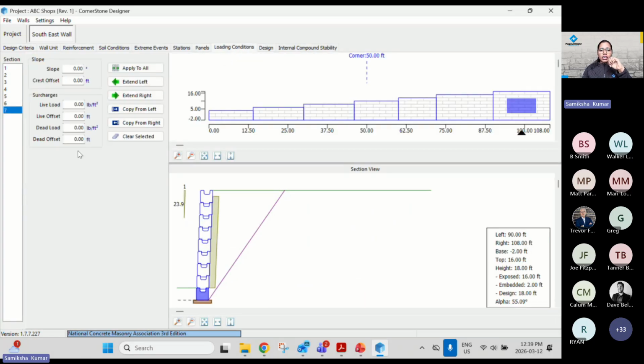Okay, now loading conditions. Very important again, very versatile depending on your project. There are certain values that are easy to assume and are practical. If you're using this project wall, let's say for landscaping purposes, but there is not going to be a vehicle on top, it's just some plantation, some landscape, 60 PSF is good. If you have a walking trail on top, 100 PSF. If you have a driveway, but only for small vehicles, no trucks, no construction, no fire trucks, no highway trucks, 150. And if you're doing the live load for vehicles, trucks, bigger vehicles, the live load changes to 250.